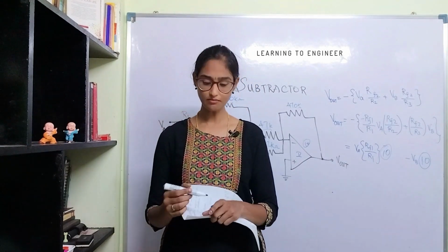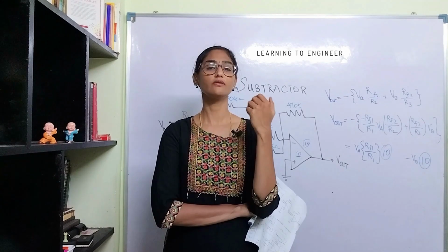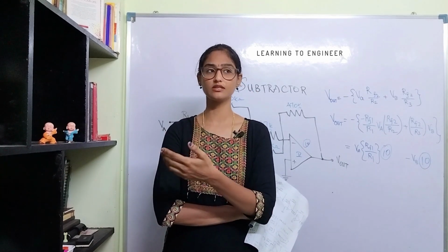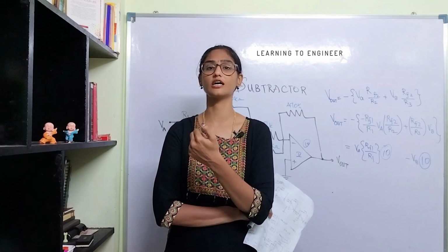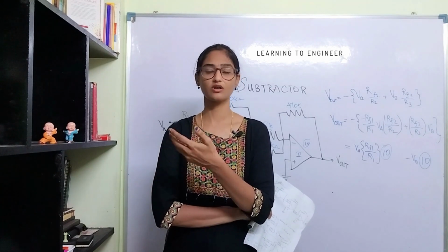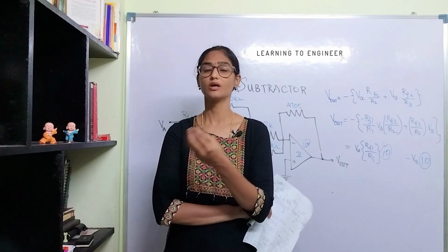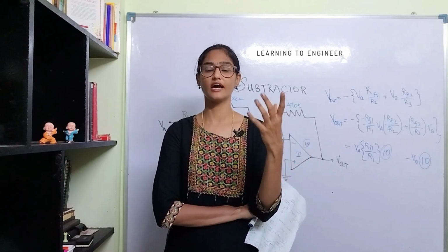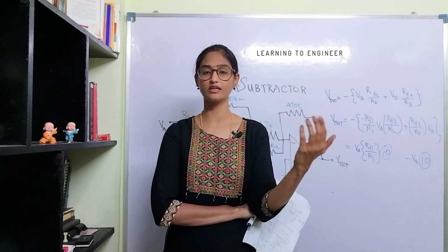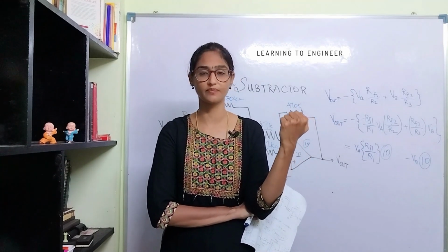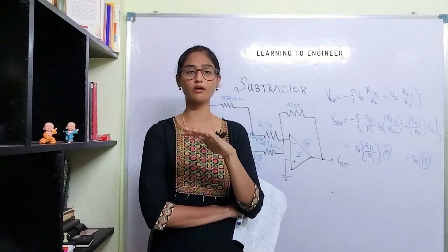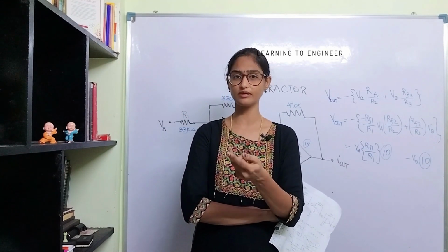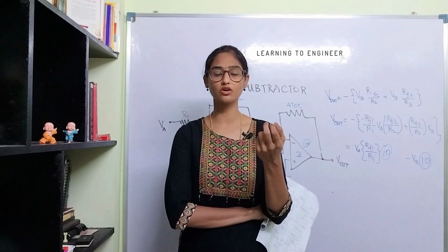Okay, so in the same manner, let us say for example, you are using a sensor like a thermocouple, RTD or some other sensor to detect a temperature or a pressure or whatever be the process parameter. You are designing the circuit to amplify this voltage and to give a measurable reading in, let us say, any kind of a meter. Okay, so you need a decent amount of amplification over there. The output from the sensor will be typically of picovolts or microvolts.